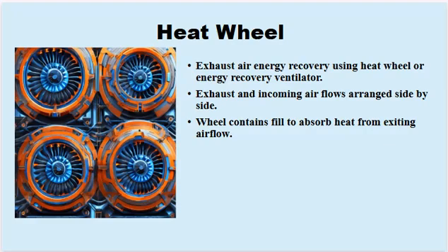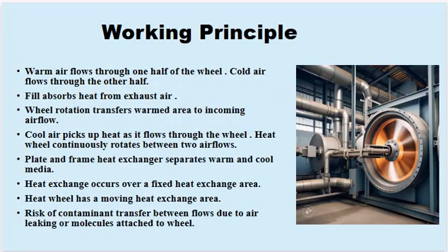Heat absorption. The wheel contains a material that absorbs heat from the exiting airflow. As the wheel rotates, the heat is transferred to the incoming airflow, effectively preconditioning the incoming air. Working principle of heat wheel. Airflow interaction: warm air flows through one half of the wheel, while cold air flows through the other half. This allows heat transfer between the two air streams.